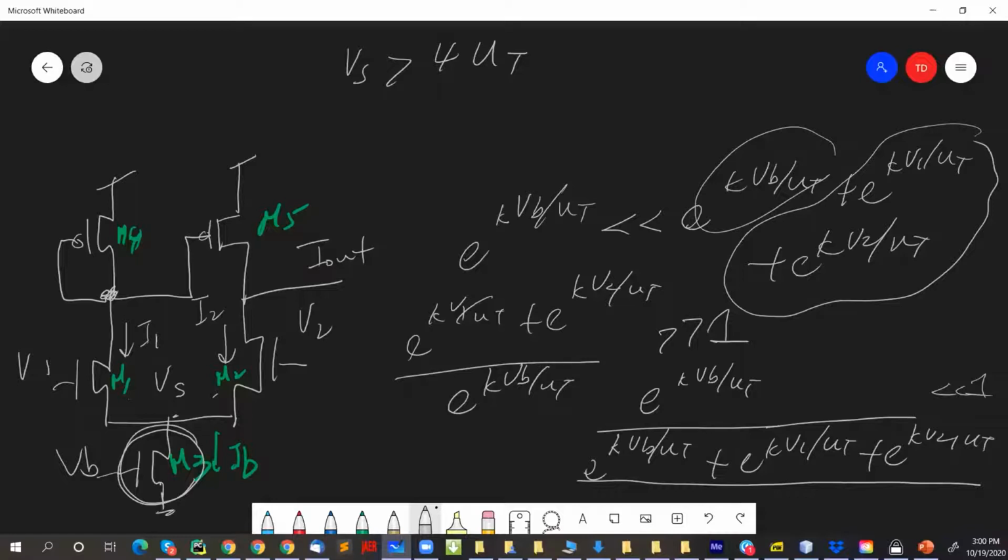Oh, I see there's a question. The analysis we're doing now seems to be large signal swings of V1 minus V2 and V2. Yeah, so for these equations I'm solving, I'm not bringing in gm, right? So it's not small signal, you're right. So you don't have to use gm for this analysis. Is that good, Chaim?